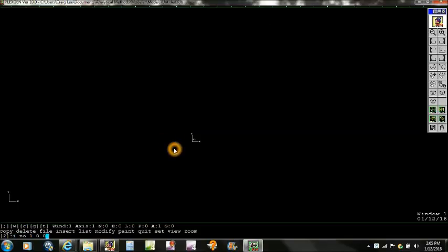The first thing we're going to do is insert a node at a radius of 1 centimeter, and then we're going to copy that node 5 times with an increment of 0.4 centimeters, and it creates 5 nodes. So we'll set our node labels on so that we can better see the nodes, and we'll paint those. Those are our first 6 nodes. We're going to zoom in a little bit here a couple of times.